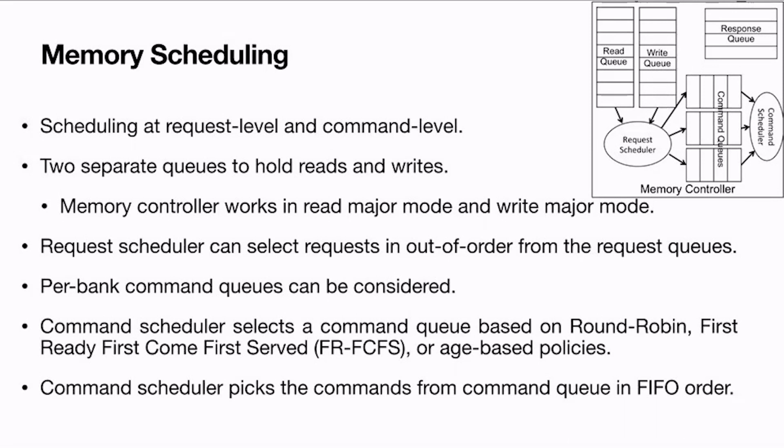That is one of the effective techniques in the memory scheduling policies, FRFCFS, or otherwise you can simply use a round robin. Just go ahead with each of these queues one after another and so on. Different techniques are there, but these are also going to determine the overall effectiveness of the memory controller. So scheduling, address mapping, refreshing, page management policies, all these are going to determine the overall effectiveness of your memory controller, which in turn is going to determine the overall performance of your system, because ultimately the data is going to be coming from the memory.